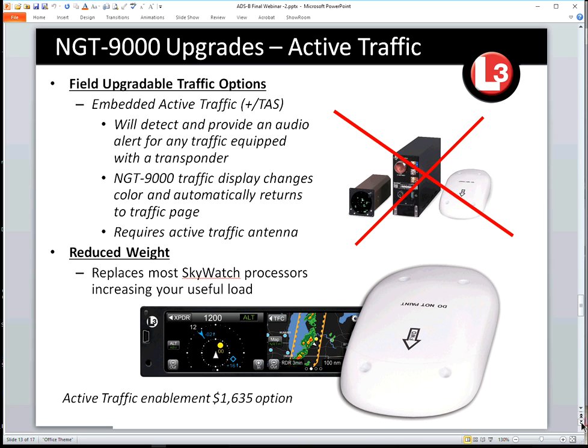And the reason being is there'll be a few stragglers out there who don't do the ADS-B upgrade. Guys in Cessna 140s out in remote areas with Mode C transponders. You can't pick those guys up with ADS-B if they're outside of a radar service area. So basically, your TCAS system could, and it's going to blend that traffic data for you.